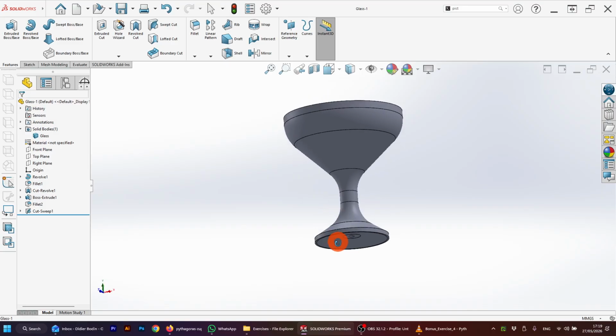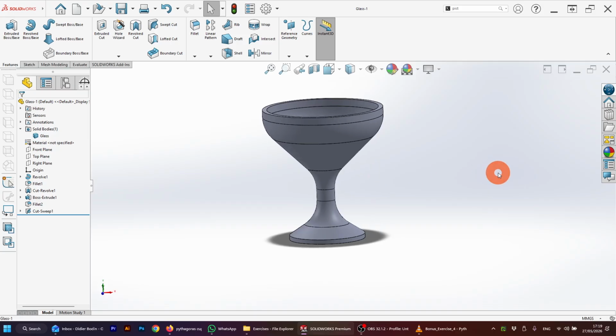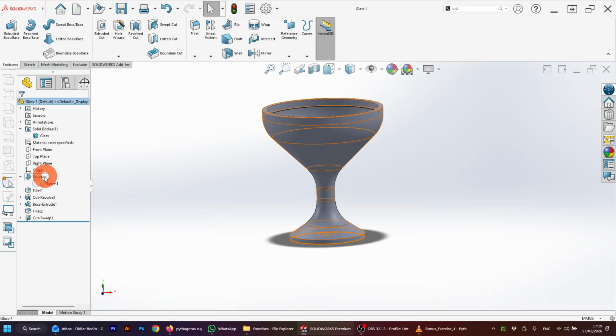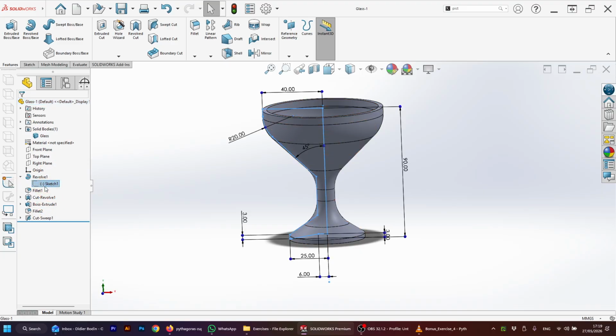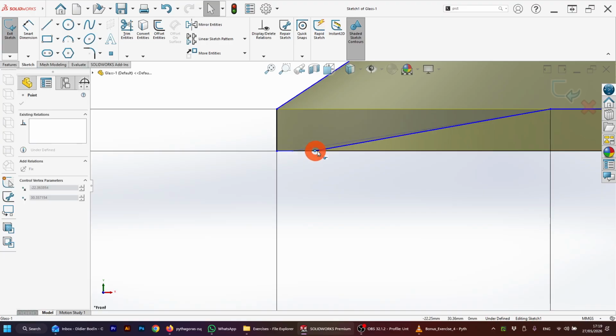And if we still want to change the overall design of the base, we can do it, but be careful, because now we're gonna play with the time machine effect. Because if I go back in time to the first function I did, any change I do now will impact the rest. So if I right click, edit sketch, and I tell it that this base is a little thicker,